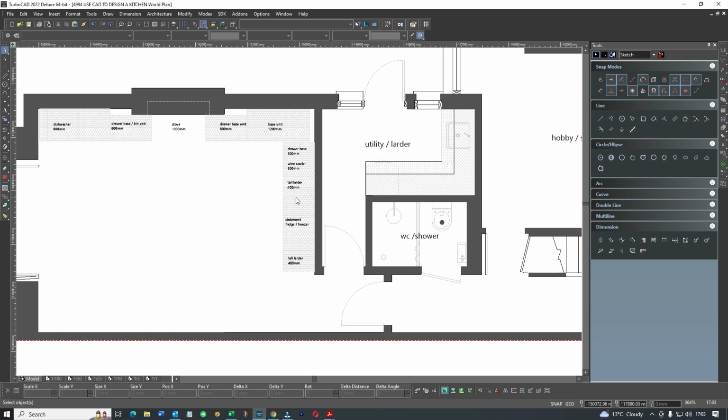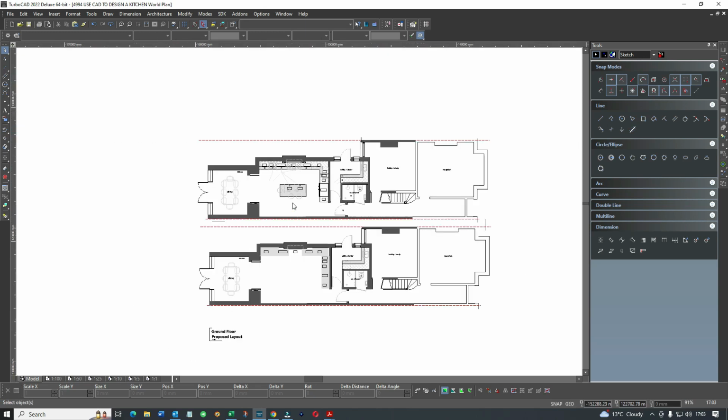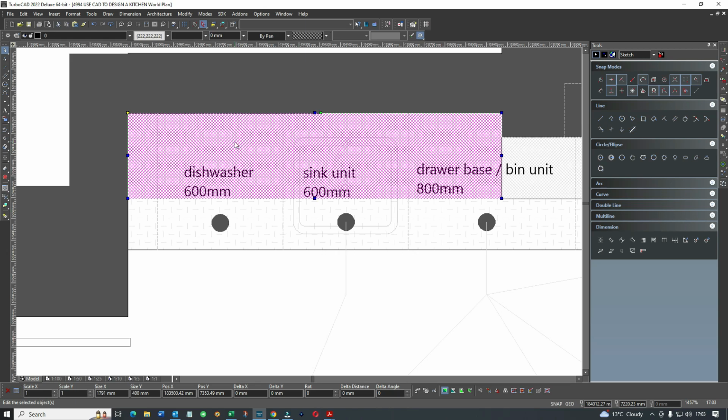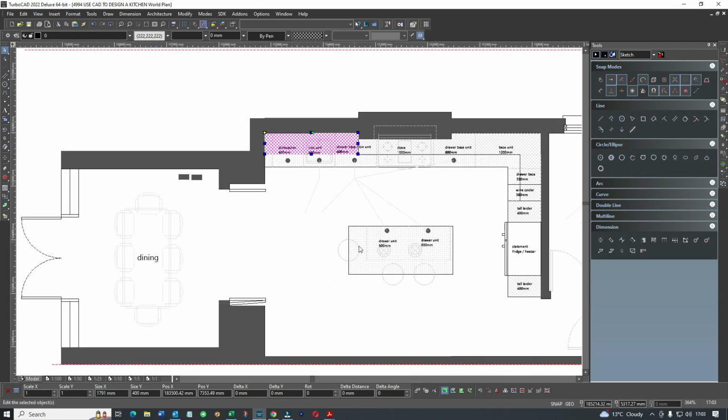But on this particular kitchen, I can do anything I want because the doors are coming from a company that provides all of the range of doors, the standard sizes, as in 3, 4, 5, 6, 7, 8, 1000, 1200, as in door widths, yeah, millimetres, of course. So as your carcass is laid out, now what we want to do is lay out the wall units. So let's have a little look at what I did here. I used this as an example, and I just drew a few lines on it.